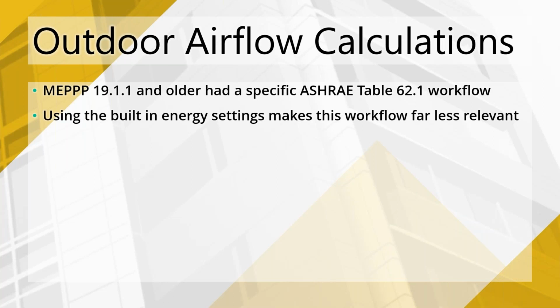If I modify those and set up my space types correctly, which are going to help me with my supply and return airflow calculations, I can also get my outdoor air calculations to work, which I think potentially makes this workflow a bit less relevant. Maybe not far less relevant, just a bit less relevant. So you don't have to have extra schedules and extra tools at play.